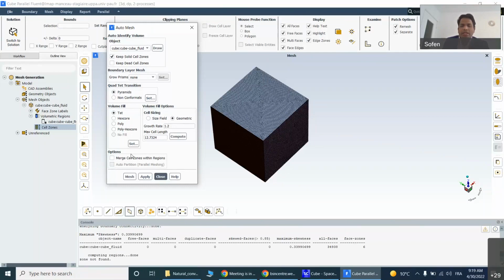In the low Reynolds number method, they resolve the viscous sublayer into a number of grid cells, and they solve the entire Navier-Stokes equation in the region near the wall. That is called the low Reynolds number model. And this uniform grid near the solid region is called the prism layer.